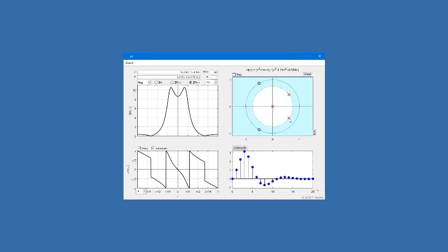By default, singularities will move in complex conjugate pairs. This is now an IIR system whose region of convergence is shown in the cyan-shaded region. And as you can see, the magnitude and phase and the impulse response have been automatically updated. You can remove a singularity by shift-clicking it.